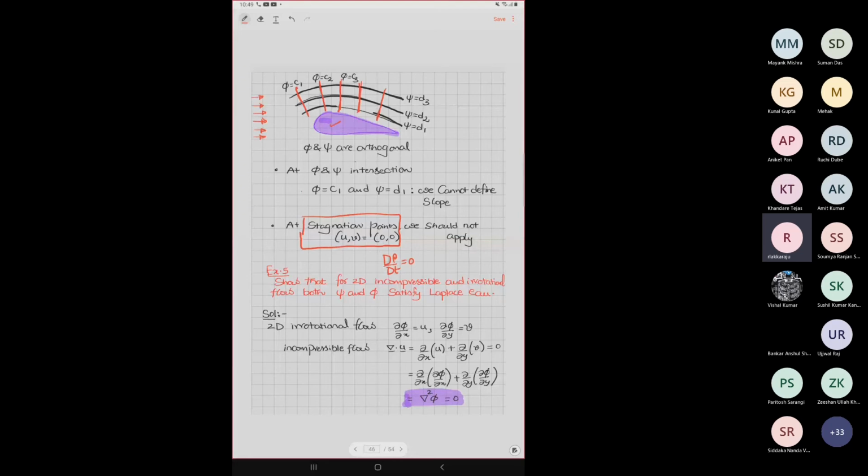If I can deduce the mathematical statement for incompressible, del dot u is equal to 0. This is also an equivalent statement from the velocity field. Though we look at a fluid particle, its density should not change. It should not change its volume, but it can deform. A sphere, whatever volume it has, it is supposed to have a similar volume even if I stretch that sphere.